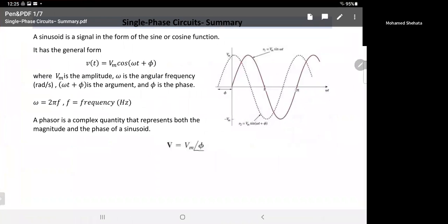What's root mean square? The physical meaning of it: you want to find the equivalent energy that can be done with the equivalent DC. So what they did, they took the AC voltage and they took a DC source like a battery. And then they took the AC and put it across a resistor. And in this resistance, they start to see the heat coming out of it. So that's the energy supplied by the AC supply.